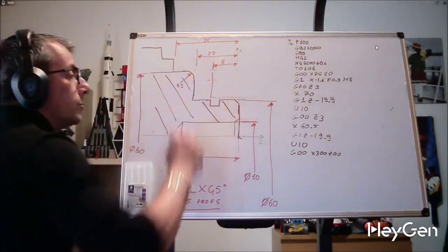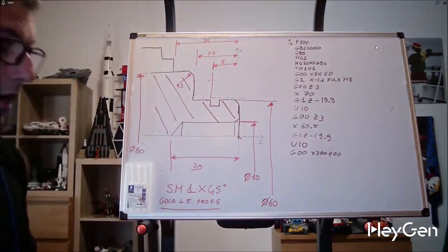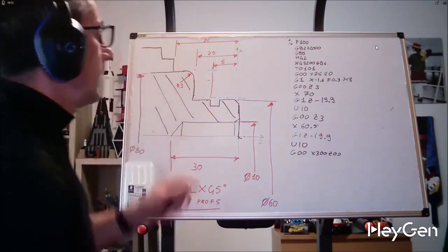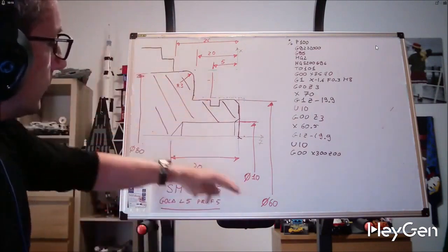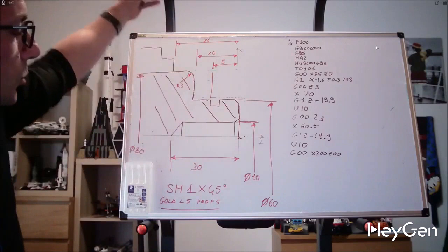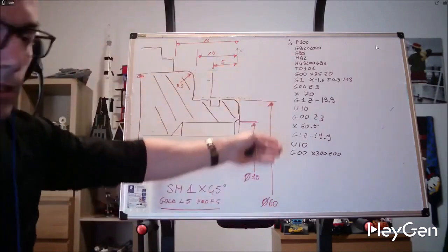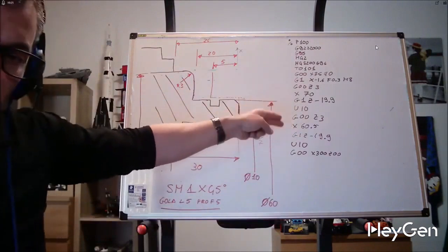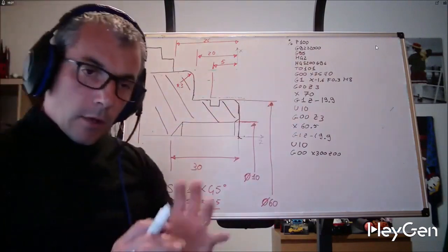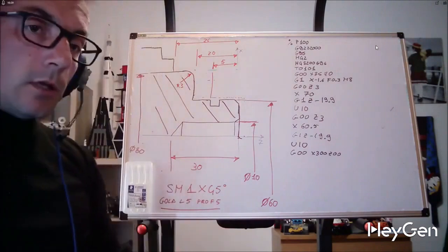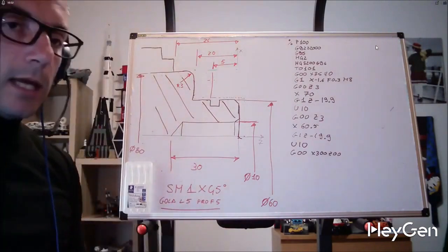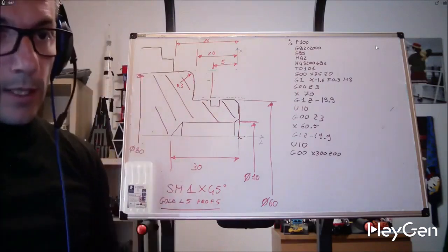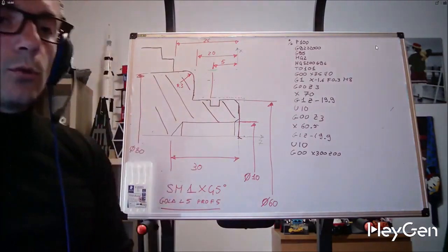It's quite a mess. Soon I will explain that it's not necessary to do all this, because if the distance instead of being 20 mm were a rough diameter of 200, reaching 60, of these lines we would need to write 1000. But CAD CAM, when they output their programs, still output them like this, because it has its own logic. Fortunately, fixed cycles exist. In fact, at the end of this brief lesson, which mainly serves to help you understand that you have already learned to program, let's talk a little about fixed cycles and introduce the concept.